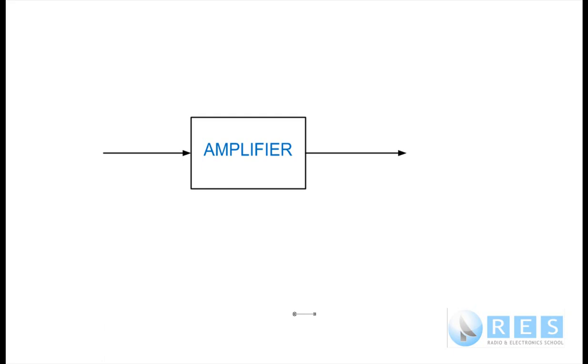If the amplifier on the screen amplified everything without changing it, so if I were to put this signal into this amplifier and I were to get the same signal out except bigger, and the shape of the signal is exactly the same. I know I haven't drawn them exactly the same because I'm not that good a drawer, but if we put a small signal in and we get the identical signal out, and the only difference between the two signals is the output signal is larger than the input signal, then this amplifier is a linear amplifier.